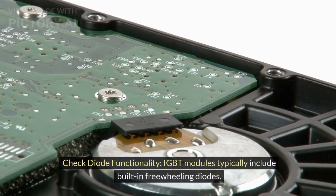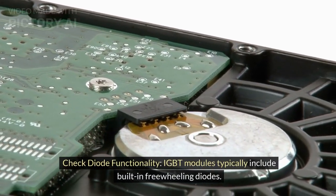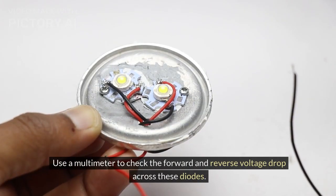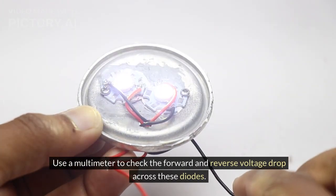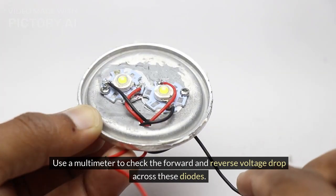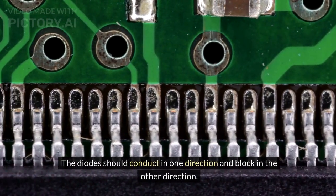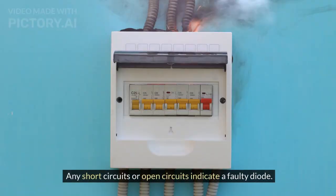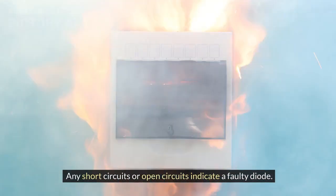Check diode functionality. IGBT modules typically include built-in freewheeling diodes. Use a multimeter to check the forward and reverse voltage drop across these diodes. The diodes should conduct in one direction and block in the other direction. Any short circuits or open circuits indicate a faulty diode.